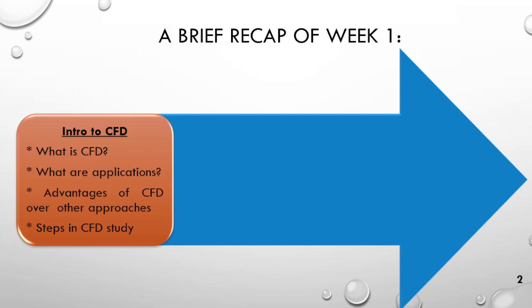Okay, so once you do that, you can identify the domain and create the geometry of your problem. Then discretize it into a small number of elements, which you call meshing. Then put the suitable boundary conditions for the domain and identify the flow parameters, and then you can do the simulation. Okay, so this is nothing but application. Now the last part is analysis.